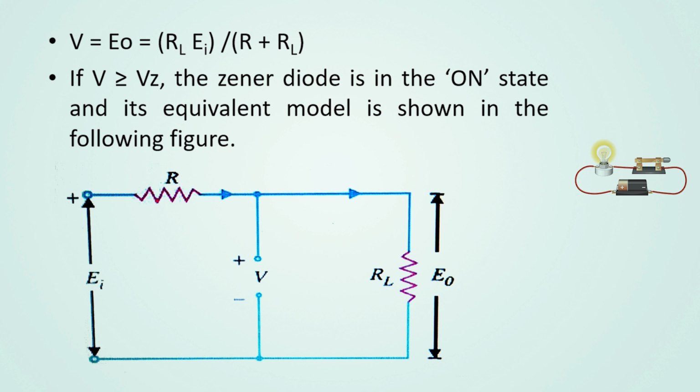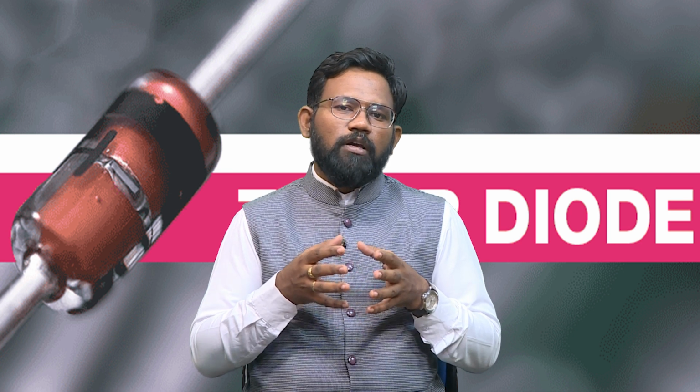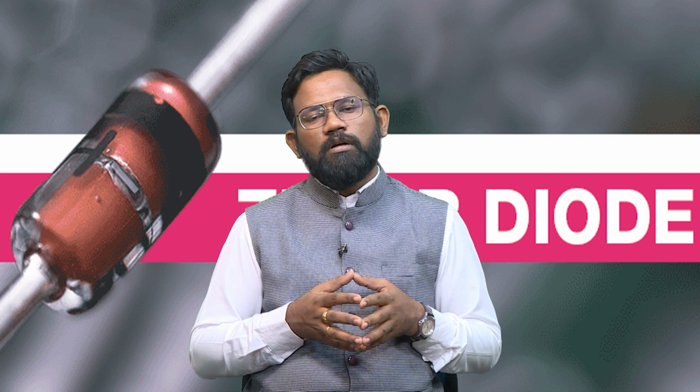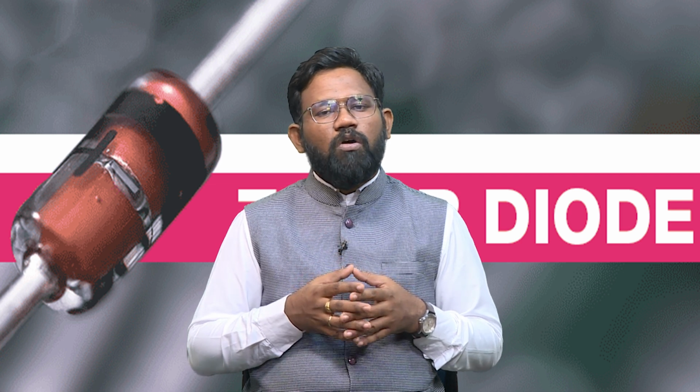Now, as we have obtained the value of capital V, if that value exceeds or is equal to the value of VZ, then the Zener diode will be in on condition, and if it comes out to be below VZ, the Zener diode will be in off condition. The following figure shows the voltage VZ, where the current flowing is IZ, the current flowing from the source is I, and the current IL is flowing towards the load.